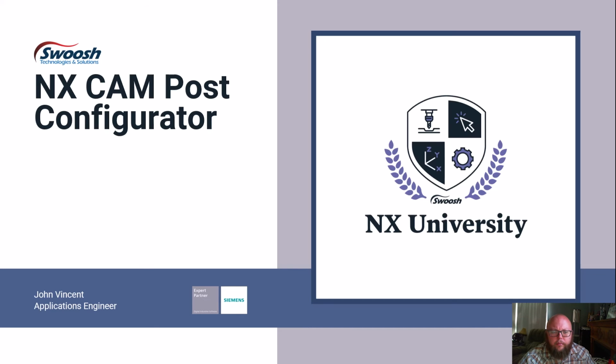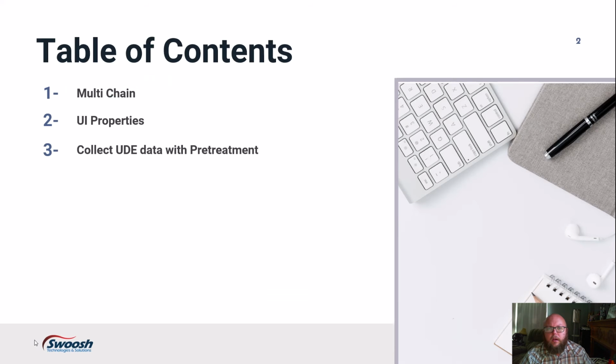In the past, we've already covered some topics about the difference between Post Builder and Post Configurator, and so now we're going to take a little step into some more detailed, more advanced topics. So we're going to do a couple things. We're going to look at multi-chain posts and how they can be used. Typically, I think about this as using multiple chains instead of multiple linked posts.